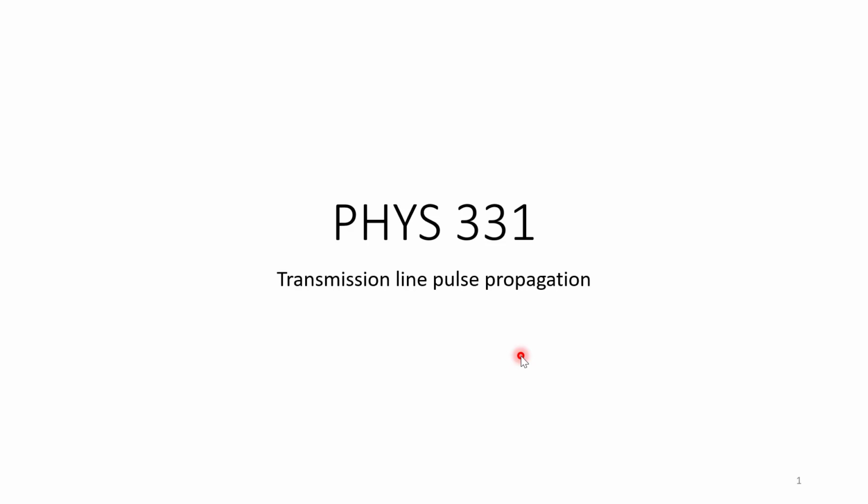In the last video, what I tried to do was a demonstration of the non-ideal properties of transmission lines. Specifically, we looked at the transfer of power through a long transmission line as a function of frequency. What we found is that when we were using 8-meter long coaxial cable and operating at a frequency of about 6 gigahertz, I think only about 1% of the power incident at one end of the transmission line was received at the opposite end. That was a demonstration of power absorption along the length of this transmission line.